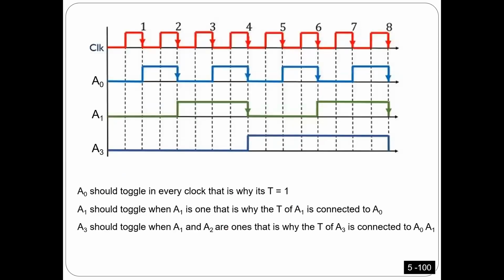To understand this observation, I made this diagram here. If you look at this diagram, guys, this is how I'm going to get numbers. Here we have 0, 0, 0, this is number 0, right? Here we have 1, 0, 0. This is number 1. Now we have 0, 1, 0. This is number 2. Then I have here 1, 1, 0. This is number 3. Then we have 0, 0. So every count is going to stay for 1 clock. It's counting, but every count stays for 1 clock, as you see here. So that's why if the clock is fast, counting will be fast. If the clock is slow, counting is going to be slow. Anyway,